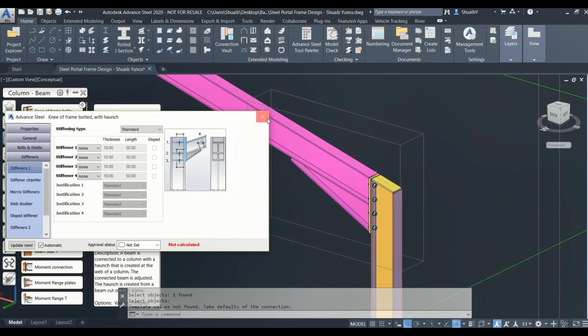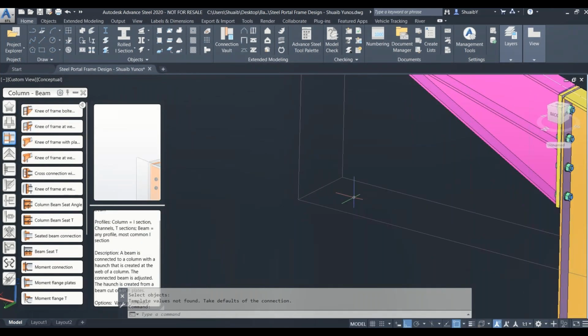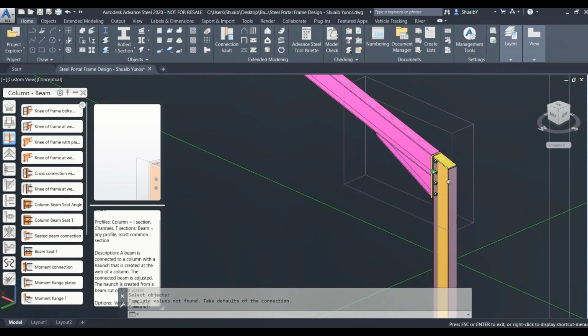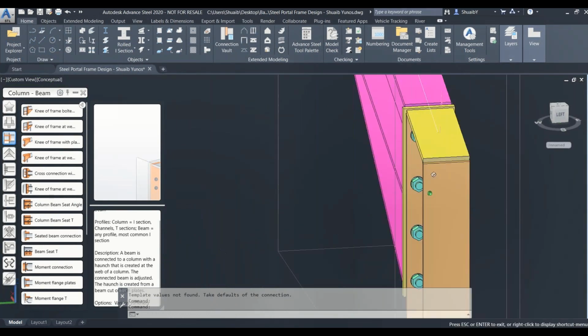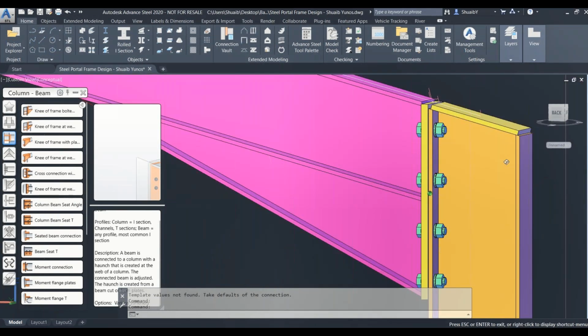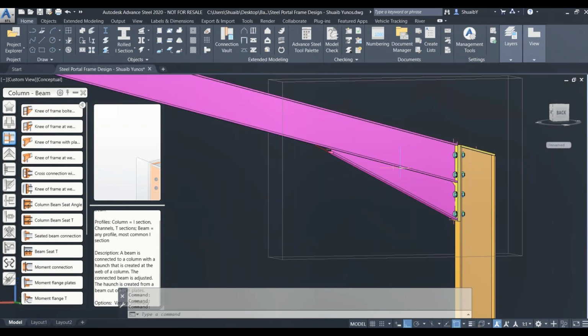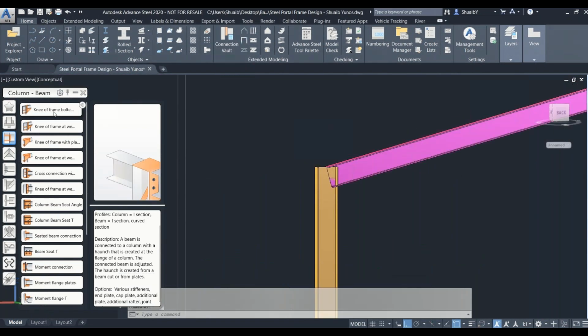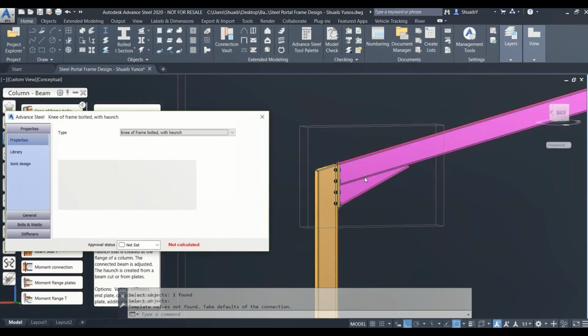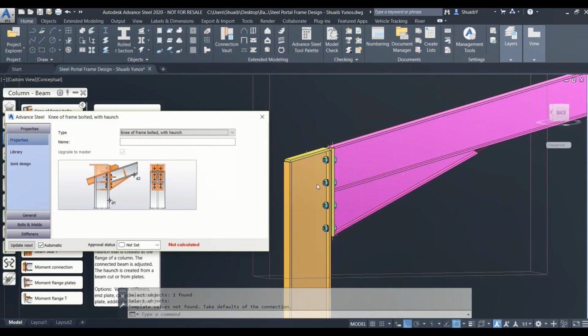Again, you can customize it if you'd like, but in this instance, I'm very happy with it. It sits in correctly. It looks very neat. Okay, you can customize it using the interface that you've seen before, right? And let's do that again in case you didn't catch it. So I've selected the column, I selected the beam on top, and you can see it has been generated.